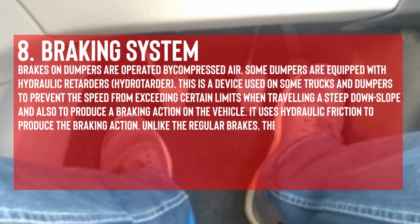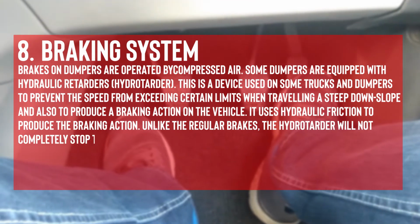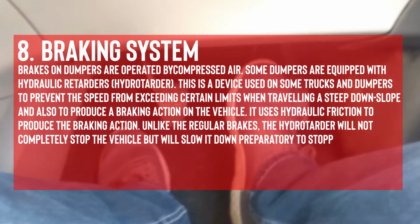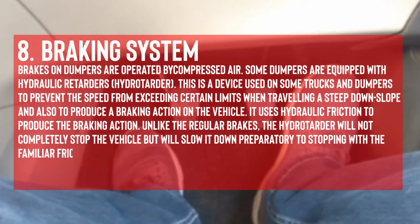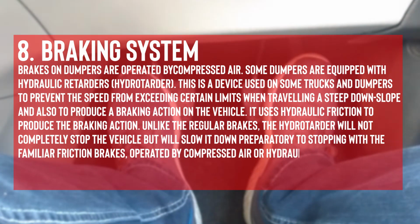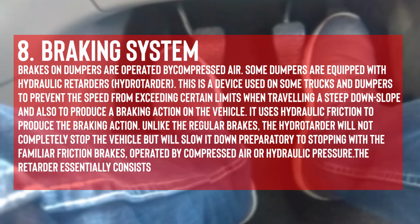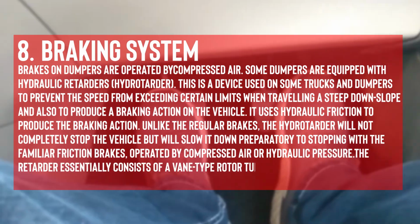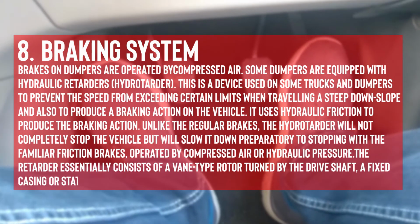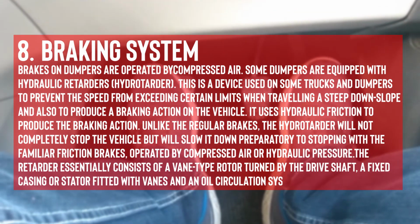Unlike the regular brakes, the hydraulic retarder will not completely stop the vehicle but will slow it down preparatory to stopping with the familiar friction brakes operated by compressed air or hydraulic pressure. The retarder essentially consists of a vane-type rotor turned by the drive shaft, a fixed casing or stator fitted with vanes, and an oil circulation system.